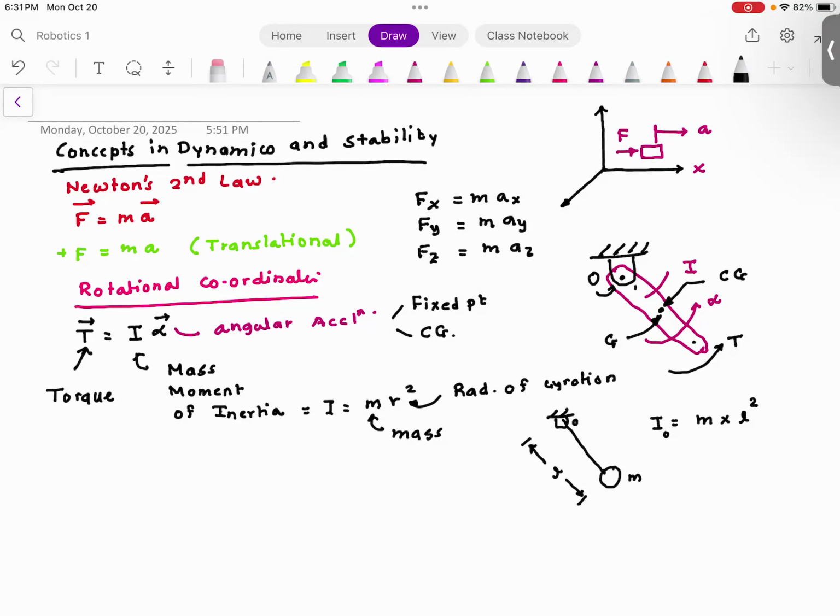The reason for that is, most robots would have some type of linkage or drive mechanism so that they minimize the load at the joint. Because if you add the motor at the joint, the overall weight of that robot would be the same, but the mass moment of inertia would be significant.